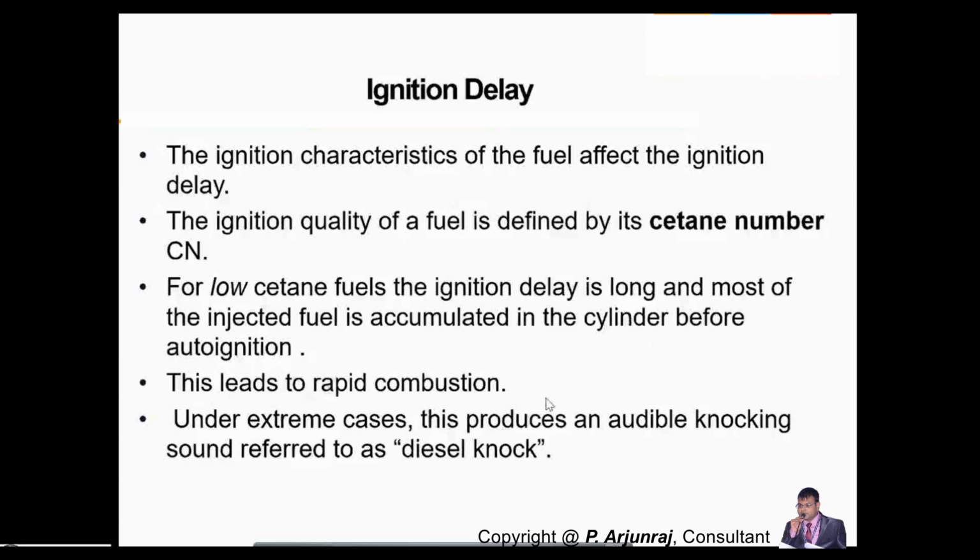There is an almost similar phenomenon in the case of a gasoline engine also, but there you have the octane number. I told you, if you have a high octane number, you can avoid knocking. Here, if you have a high cetane number, you can avoid a long ignition delay.